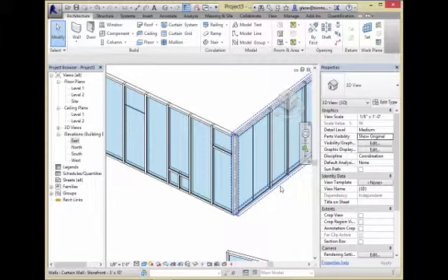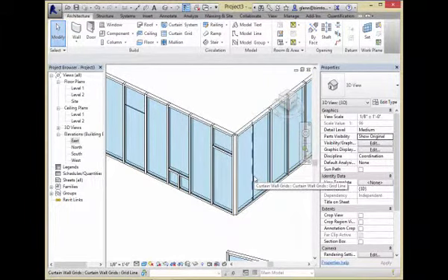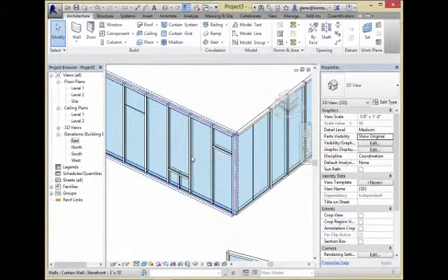So how that works is if you hover over something, that actually did a pretty good job. I can tell that it's choosing the grid line because down here in the status bar it's suggesting that's what it is. If I hover over this piece over here, it's a little more ambiguous. In fact, I'm looking at the mullion. If I want to get rid of the grid line that's under there, what I can do is tab, got the whole wall, tab, now I got the grid line. But you might have to tab sequentially through that, and it will take you through different options. When you get the piece you want, if I want to get rid of that grid line, I select it, and then I can go ahead and take it out.